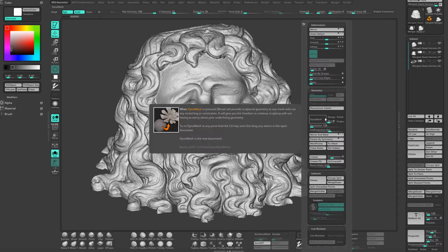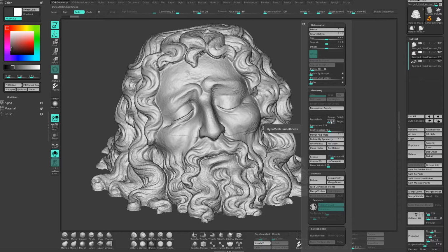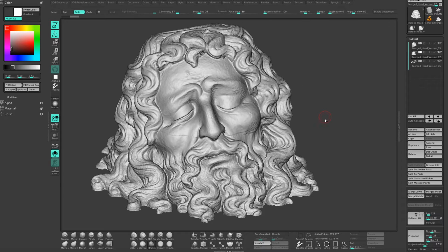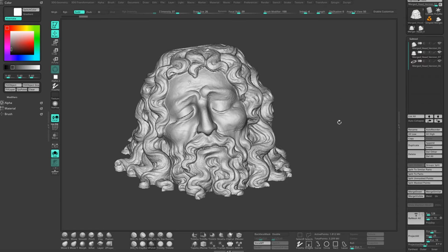So when I bring up my custom menu here and set the dynamesh blur value down to 0, for the resolution slider, there's a little bit of guesswork involved now. Maybe 1500 is already too high, so let me try 1K, and I click on dynamesh and give ZBrush a few seconds to make its calculations. And there we have it, our dynamesh.